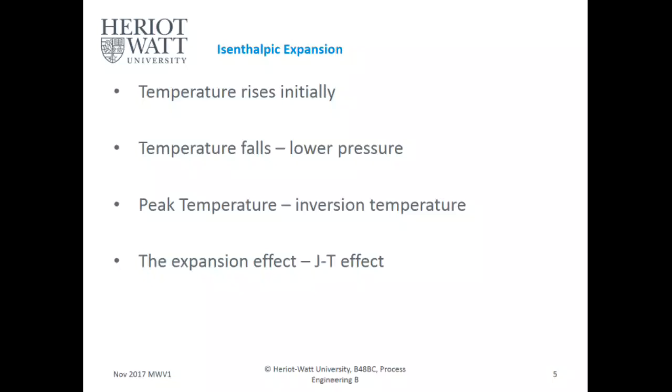As this blockage builds up, and then when you heat it up to remove it, it can shoot through your pipe going 300, 400 kilometers an hour. When it hits an elbow, it's going to be a major explosion. A lot of people will die. So remember Joule-Thomson effects. It affects quite a few other things, but we'll go back to chemical processing in a bit.